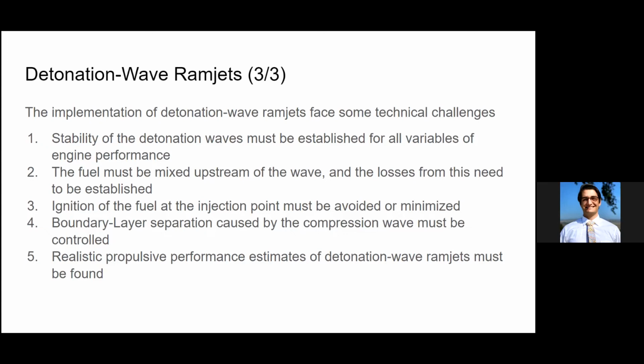Also, boundary layer separation caused by the wave itself has to be controlled in order to maintain inlet feasibility, and you need realistic propulsive performance estimates for detonation wave ramjets before actually being able to use them in reality.